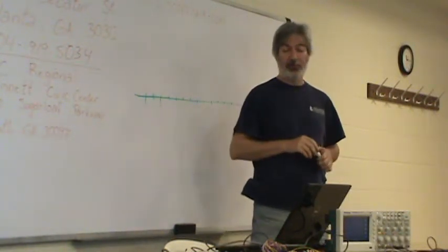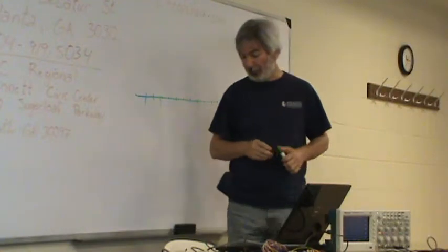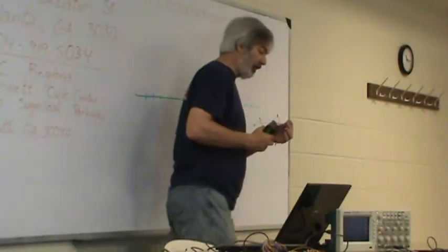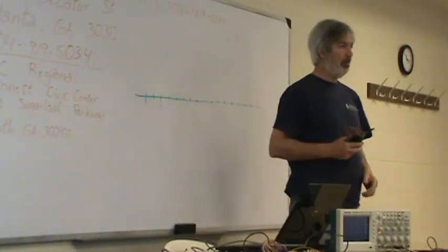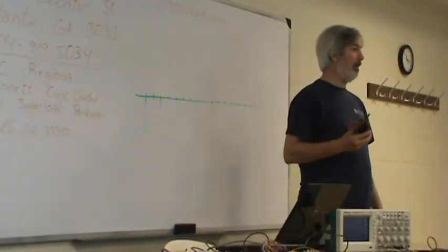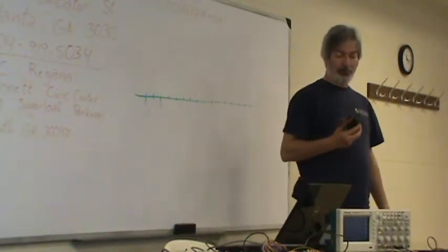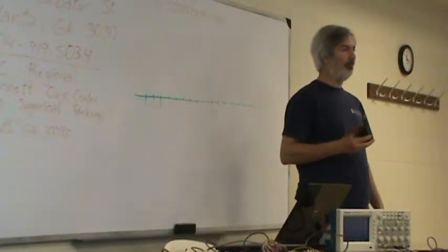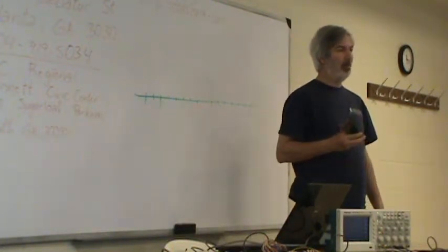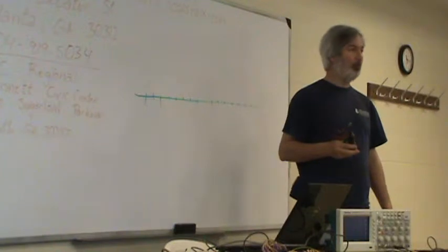One thing that you may do, for example, during the show and tell, I was showing off my handy dandy little voltage regulator. Like I say, this particular one will output an amp. What's going to happen when I pull an amp and a half? If you pull an amp and a half from an older linear regulator, you may very well simply smoke the regulator.